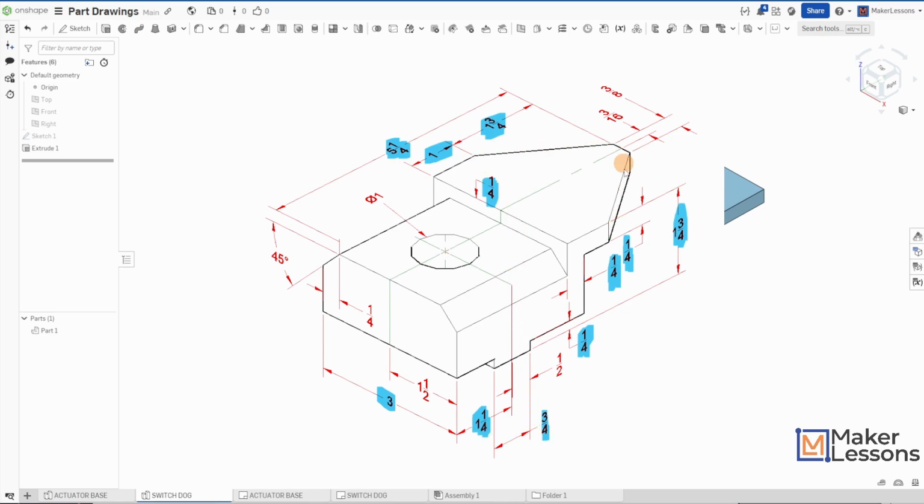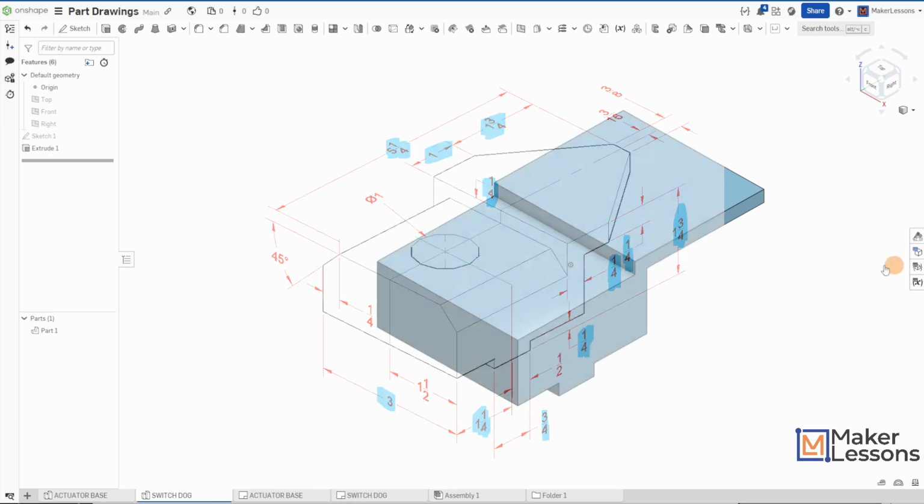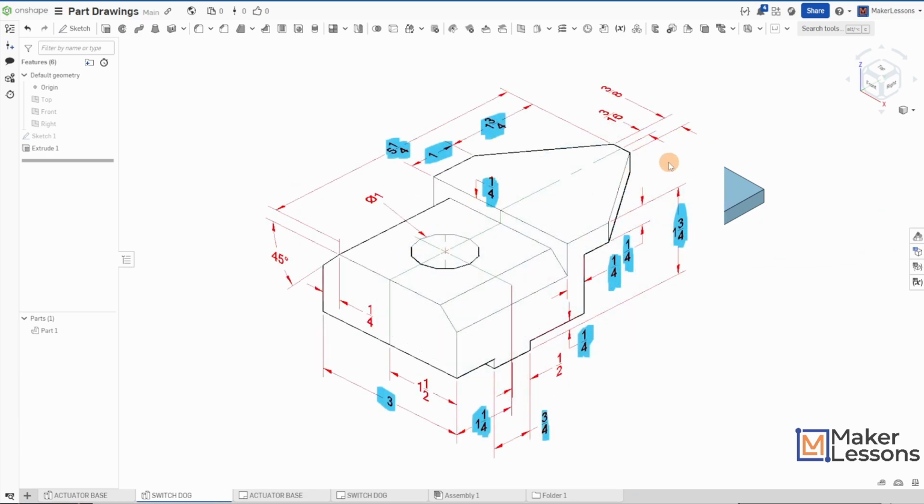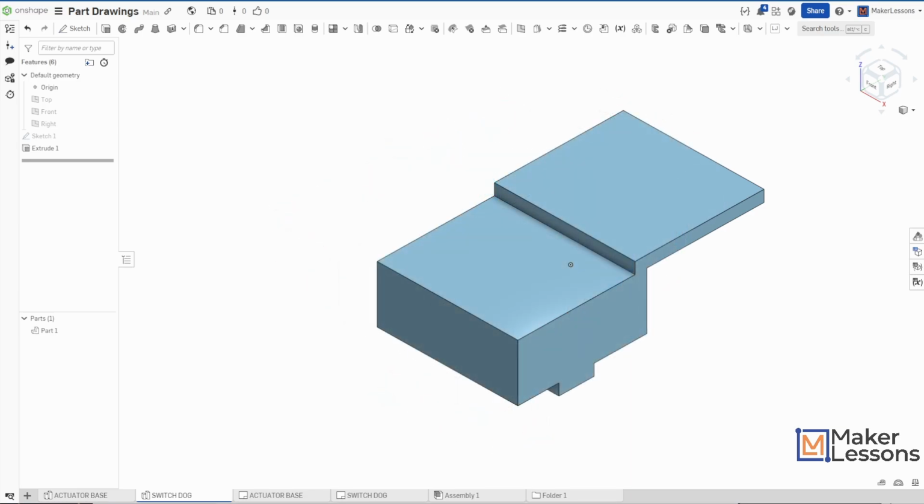So we get this little wedge here, and then we're actually gonna do what's called a chamfer for the edges on the side. What are our values? Our values here, I'm just going to draw a line and then hit this with a 1 and hit that with a 3/16.